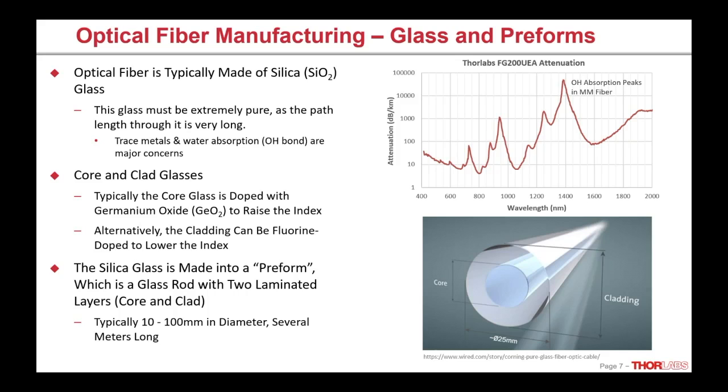Windows are going to be a couple millimeters or a centimeter thick. And that greenish tint is due to some iron oxide contamination within the glass, trace amounts. Now, for a window, that's fine, no big deal. Even for something like a lens or a scientific window that you might use in an optical setup, the optic's only going to be a few millimeters thick, so trace absorptions might be okay.